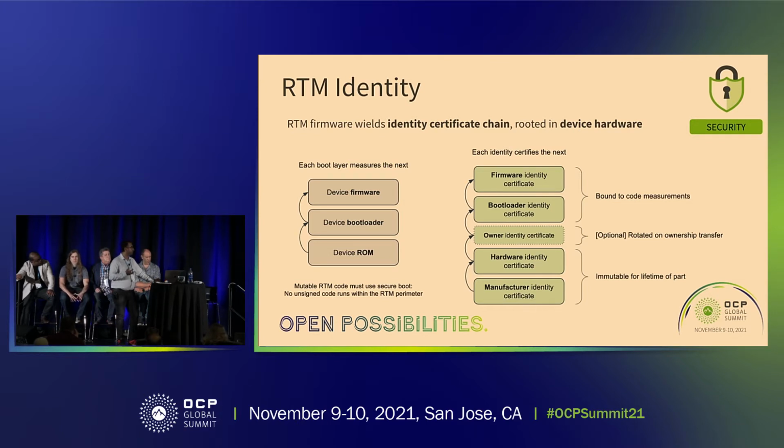These must be immutable for the lifetime of the part. These would then be used to establish an owner identity during the ownership transfer process. And finally, at runtime, we would bind these together along with the bootloader and the firmware identity of the device to establish a trustworthy, unique, and immutable identity in our infrastructures.